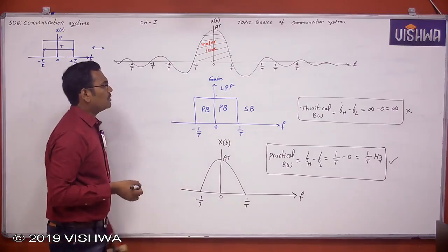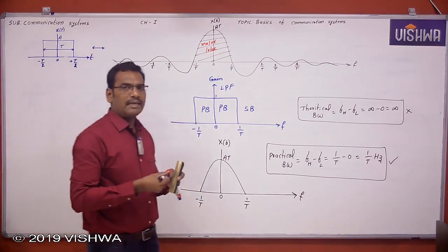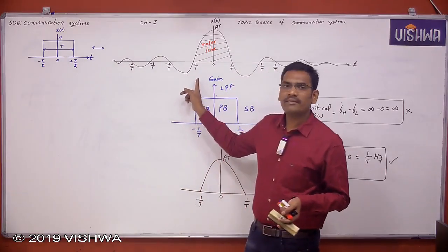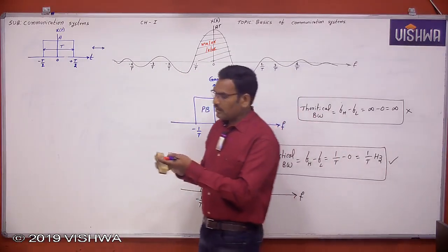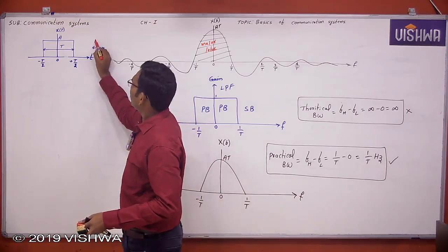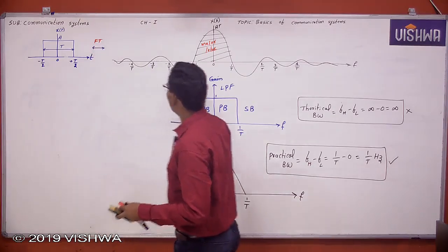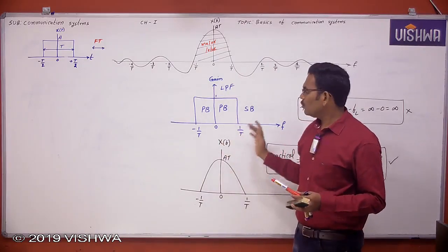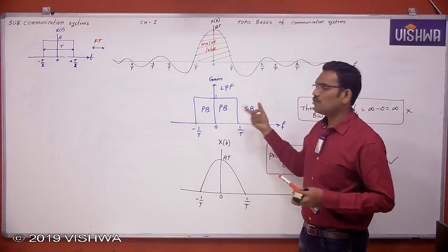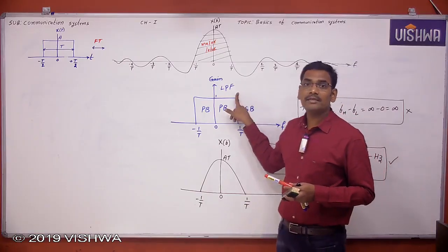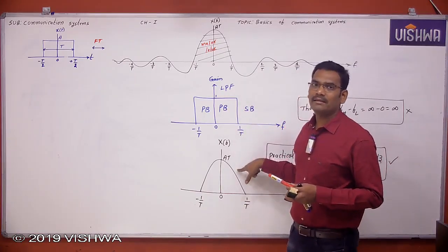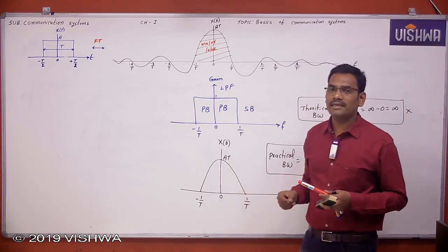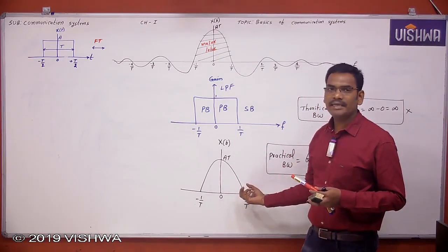Okay. So this is the way you calculate a time domain signal into a frequency domain signal by using the Fourier transform. And if there are any limitations in this particular frequency selection, use the appropriate filters to band limit the signal. So what you can understand here, the low pass filter is used for band limiting. So here the infinite bandwidth is limited. A band limited signal is nothing but a signal which has a limited bandwidth.